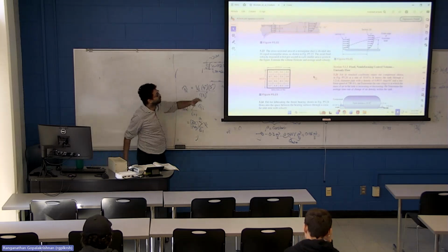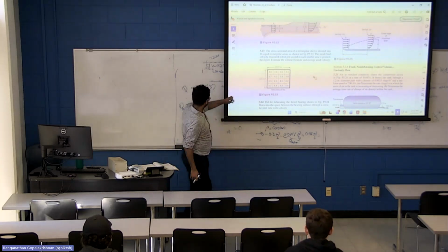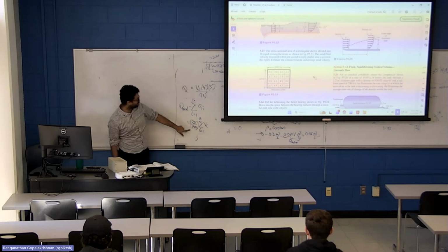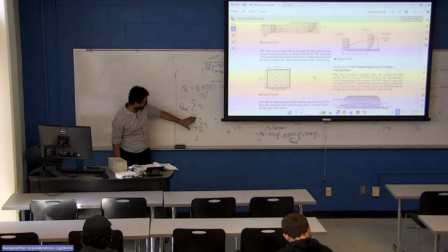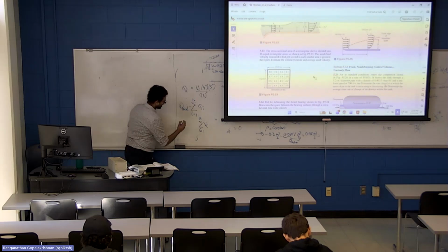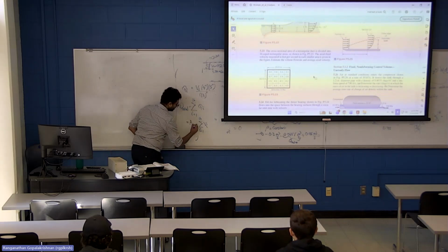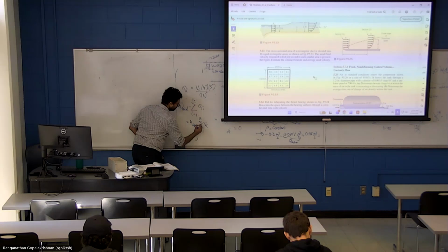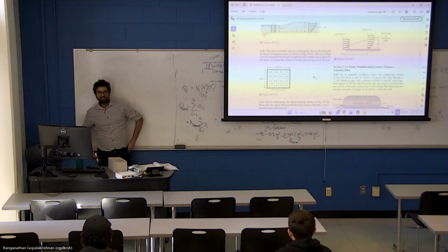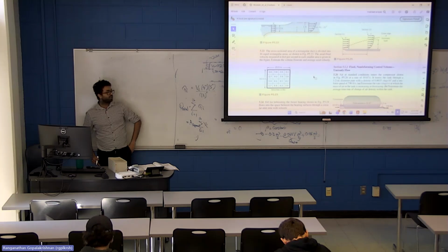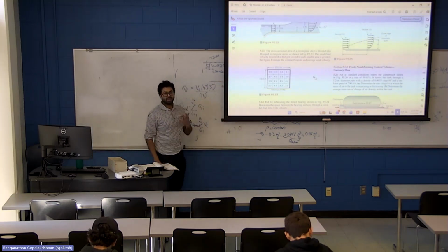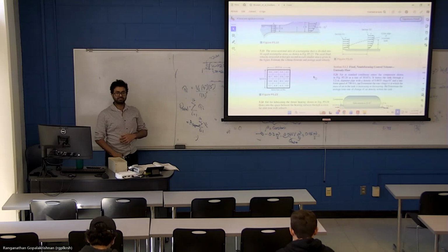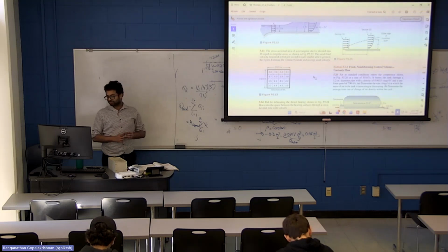Okay, so estimate total volume flow rate is summation of all the velocities multiplied by the area of each segment. So I'll write this sigma Vi times area of each segment. How do you define a total average velocity for the entire duct? How to think of an average? What is average?